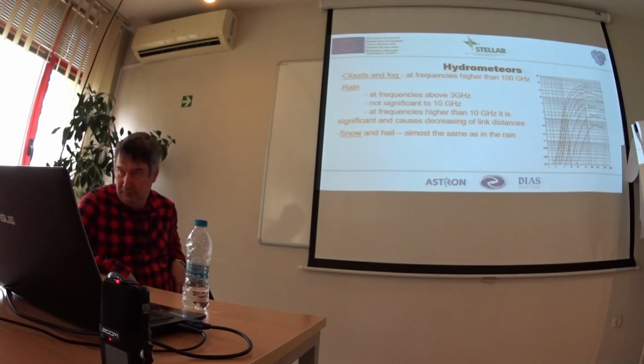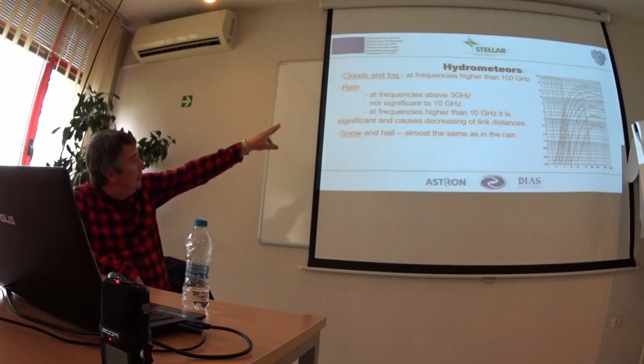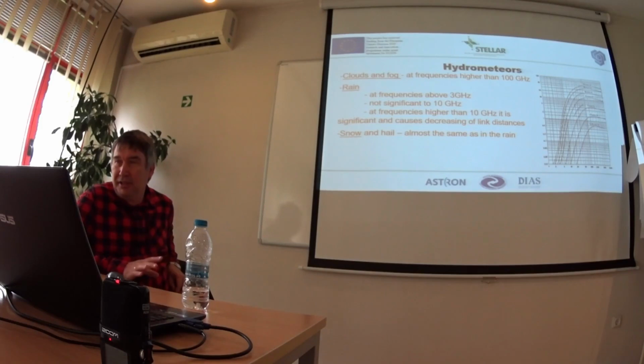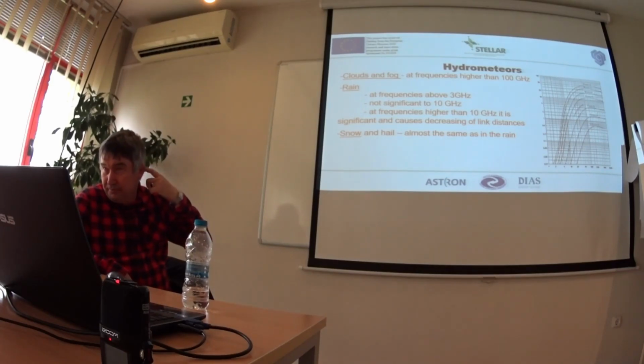Rain. This is the most frequent phenomenon connected with hydrometeors. It affects radio waves with frequencies higher than 3 GHz. For lower frequencies, practically there is no attenuation of radio waves in the hydrometeors.